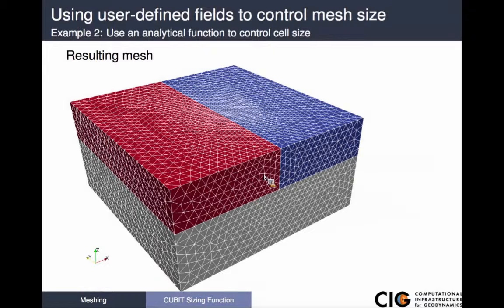Yeah, I do believe it works with quads, right? It works with quads and the paving scheme and triangles and the... It works. Basically any of the ones where you can do the biasing functions. So this is really a replacement for specifying the grid size along curves. Yeah, it's just you're specifying it through the volume rather than along a curve. Yeah, okay. Oh, I guess that's it. So anyway, we'll go ahead.